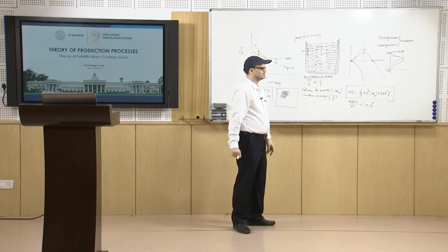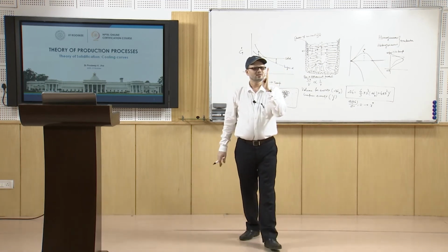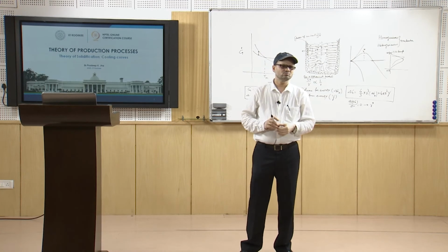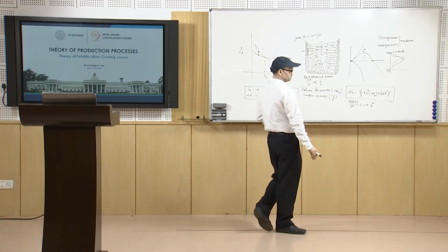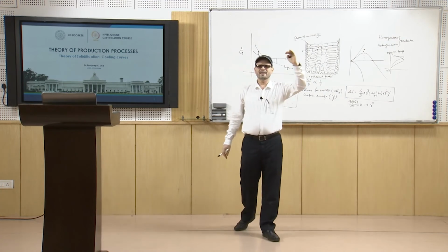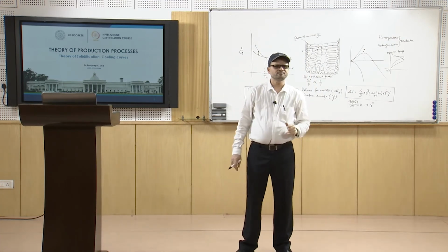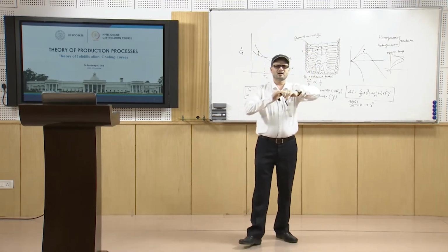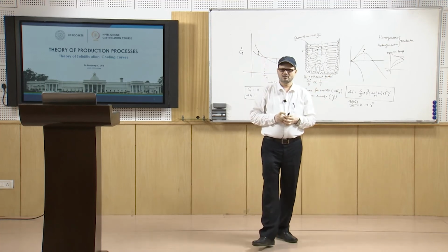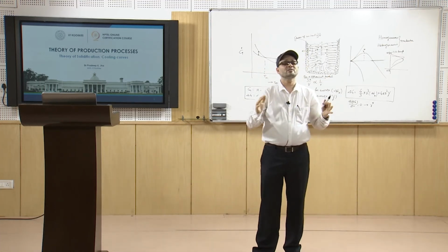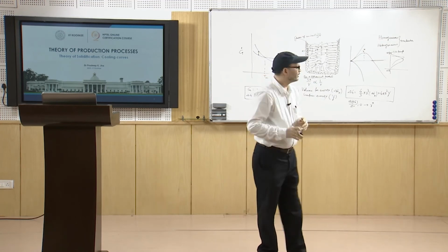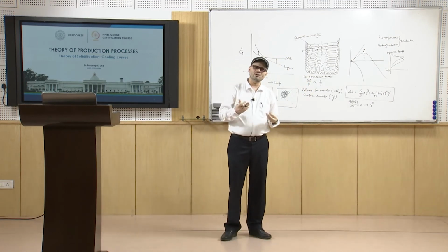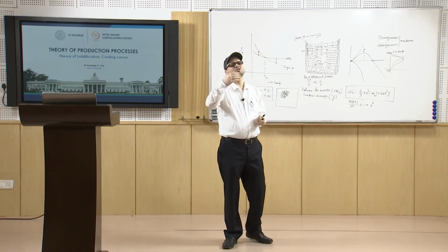In the case of alloys, you do not have that demarcation available, because alloys do not solidify at a constant temperature. In the case of metals, they solidify at a constant temperature. So, once the temperature reaches that temperature, it stands still till the transformation is finished. Now, in the case of alloys, this does not happen. So, what happens in the case of alloys? For that we need to know the cooling curve.